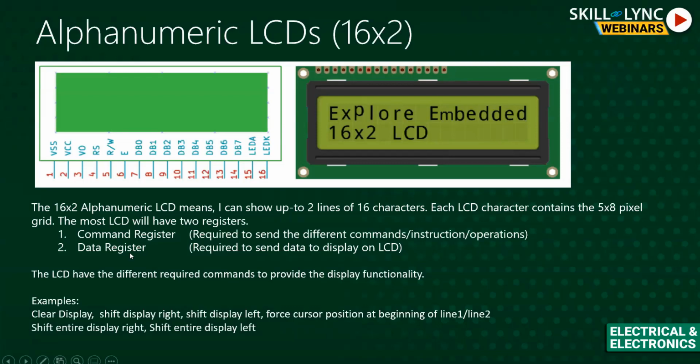The LCD will accept either a command or data. If we need to send a command or some instruction, we need to use the command register. It is required to send different commands, instructions, and operations, in which we specify that it should operate in this way or that way. So there are specific commands we need to send to the LCD.